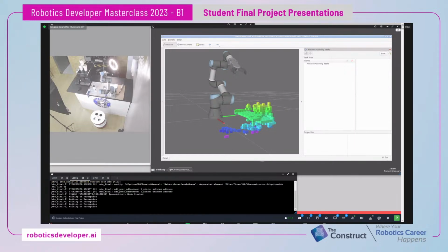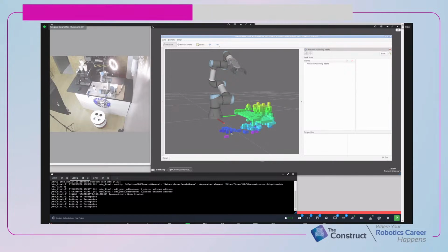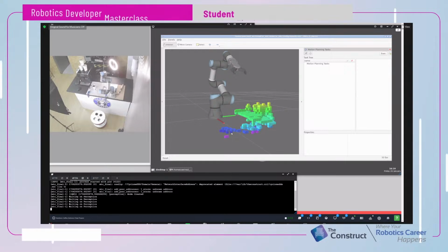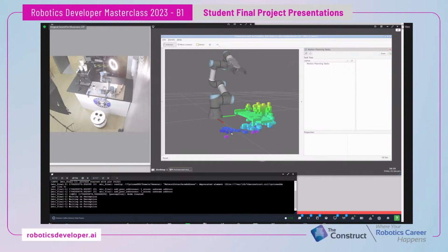So normally you might expect that if you have action A, B, C, that you would plan them in order A, B, C, and execute them in that order. However, due to the way MoveIt passes information in the stages, sometimes you might plan order A, C, B, and then it'll actually execute order A, B, C.